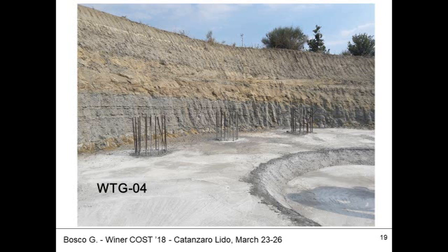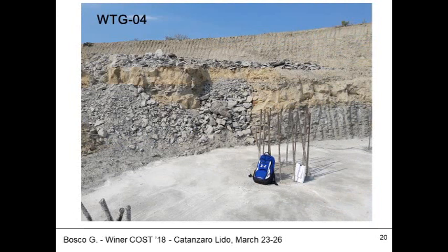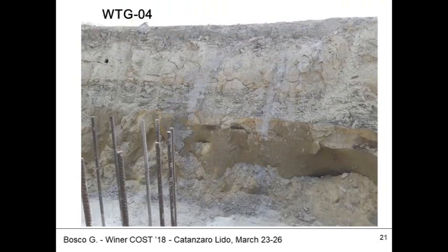Very likely pore water pressures are negative in this environment. We have not encountered water. Very likely water is down below towards the valley areas. So these materials are either unsaturated or saturated with very low pore water pressure. And so estimating the strength is only possible through an unconfined compression test or triaxial UU test. And we used the undrained shear strength to determine the lateral shear strength along the piles.